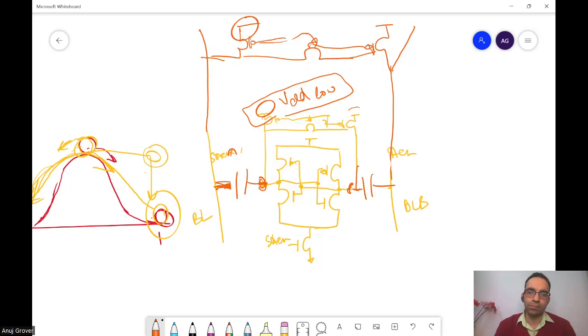Okay, sir. So the coupling has been replaced from a resistive coupling to a capacitive coupling. Yes, sir. That is why. Okay. So earlier, when there was a pass gate, when there was a PMOS over there, then it was a resistive coupling. Now it is a capacitive coupling. Yes, sir. Understood. Okay. Thank you.